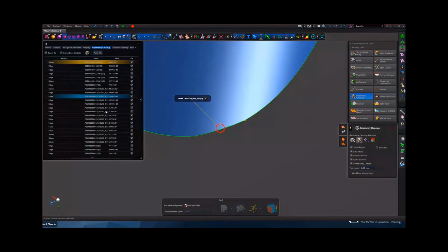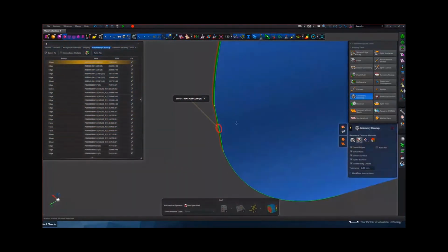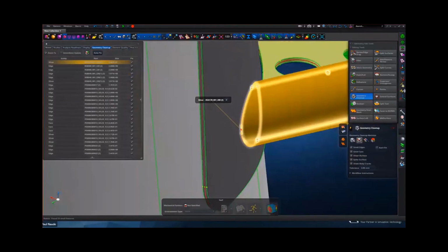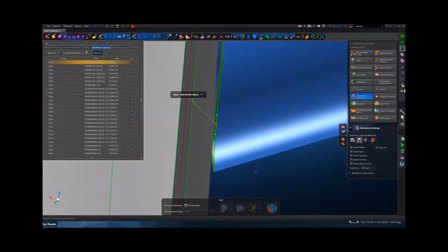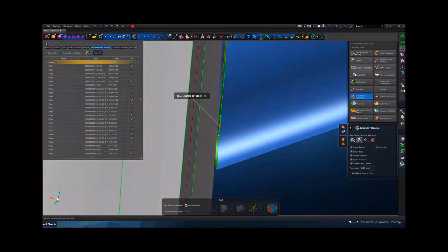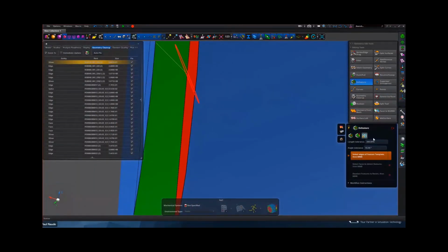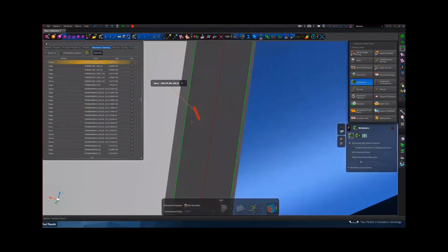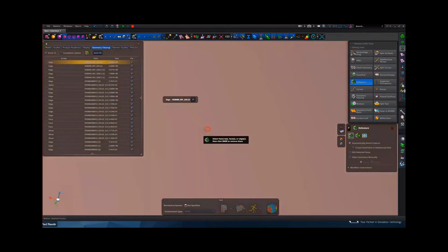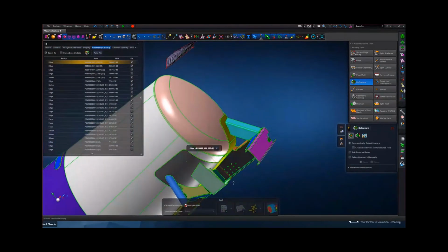So there it has now actually found this sliver. Oh yeah, before I only cleaned up the mid-surface model, I didn't have the solids visible. So now it actually shows me that there's a little defect in my original solid model that I wasn't even aware of. And this is very, very useful to know. So now I can come in, let's just get rid of that feature and see if we can delete that. Right, so now this is done and we can jump to the next one. It automatically zooms in if you have that open. So let's see what this was all about.